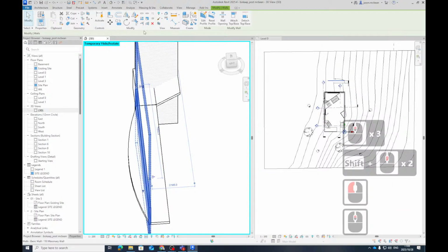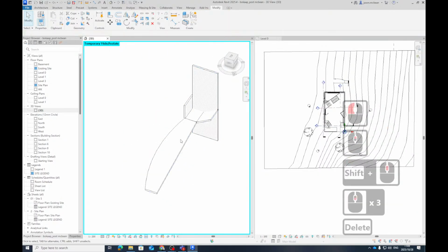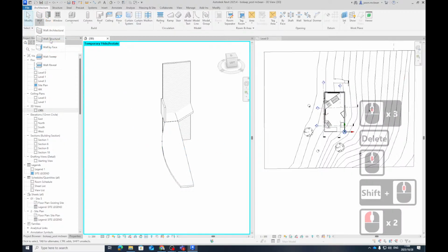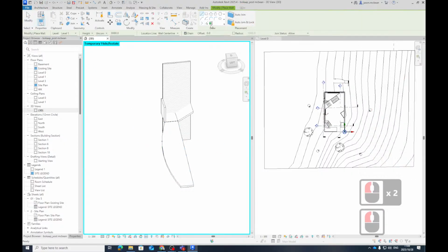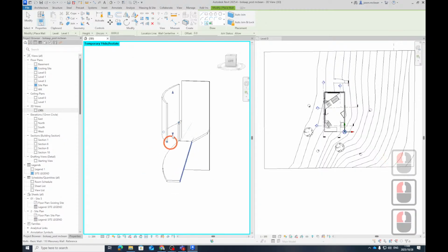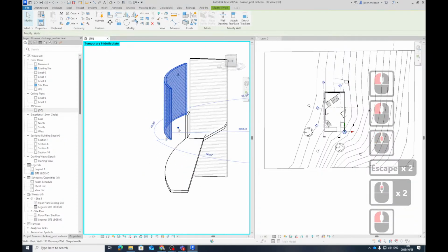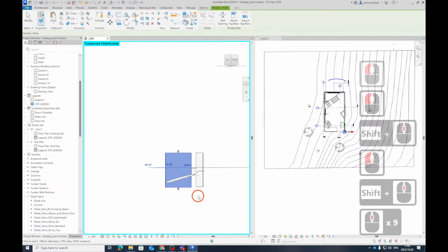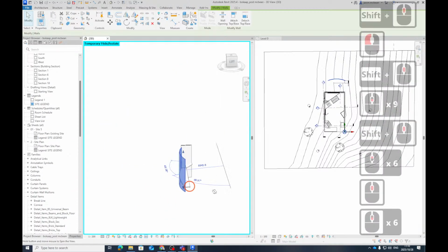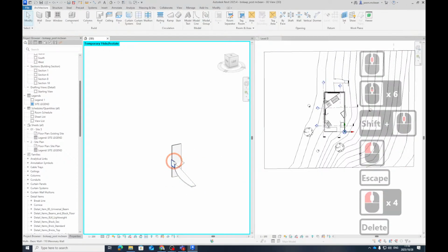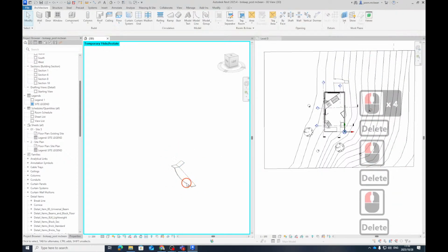So now I can also make this follow the profile. What I do like about walls now, I can go architecture, wall. So I'm going to say architecture, wall, and I can use the pick line tool again, and it will follow that profile. This is what I do like about walls. And then you can do that cut thing again, and you can do that whole exercise again, and it will follow it. Try and do that with a handrail. Again, you'll be crying. The maths involved. Okay. Tried it at some. No, it's very tough. So just use your floors.